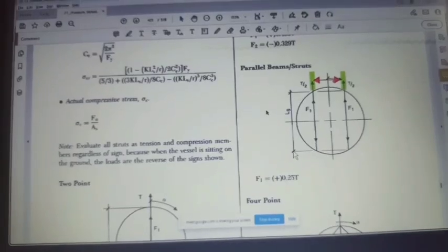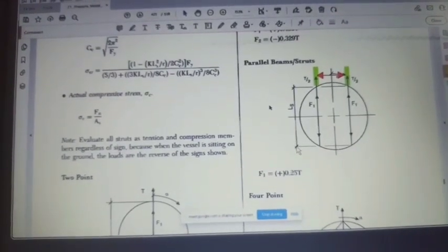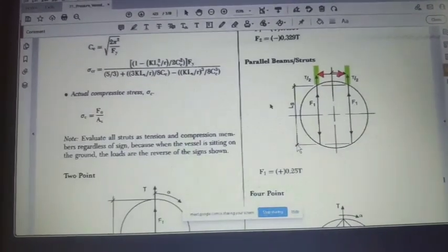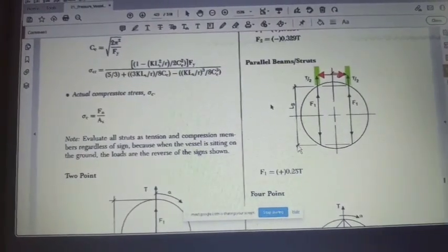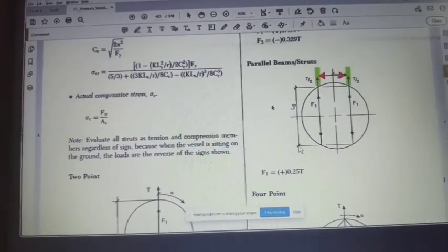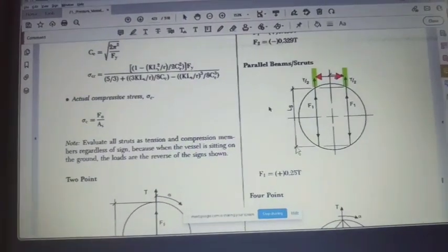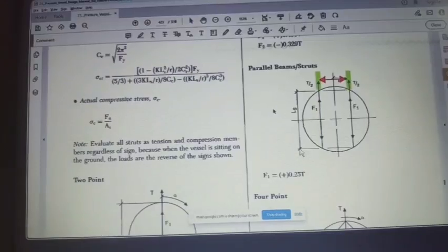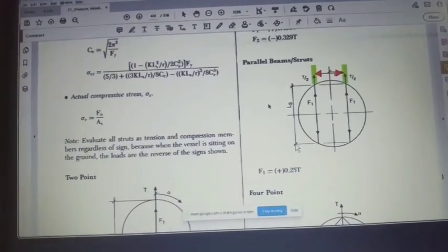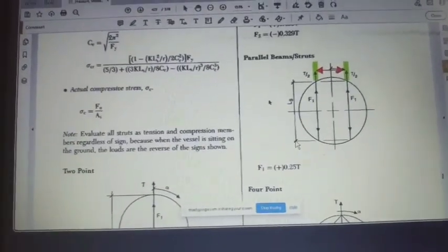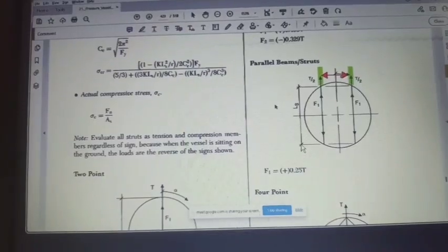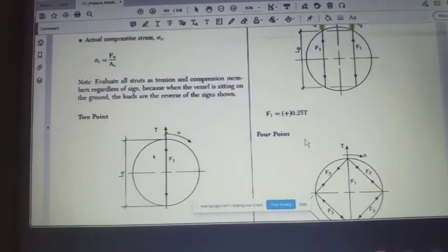Why are you not using this one? Okay, I can use this one, but my point is the lifting beam, I mean the tailing lug, can be here in the middle. No, you will split it. I'm coming to that point. You use the word lifting, but I guess you are talking about the tailing portion, right? Tailing beams, yes. You can use 2 tailing lugs and the tailing load will be divided, and you can do finite element analysis if required, and then the design will be good. But the problem is that right now my distance is only 250.